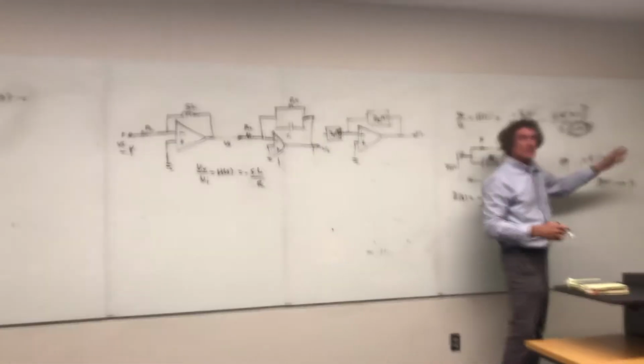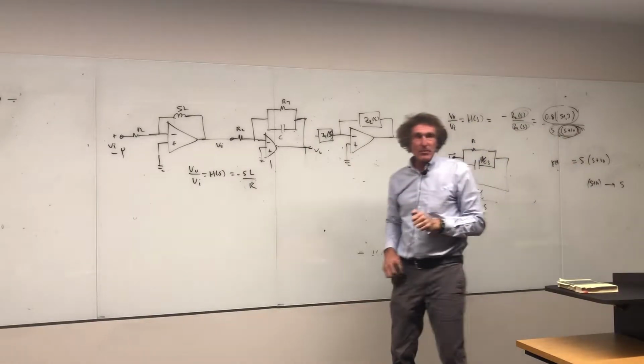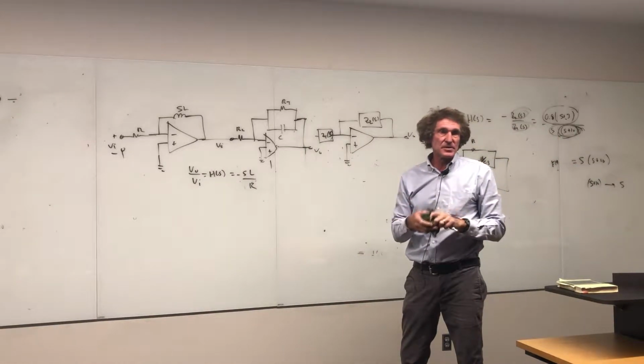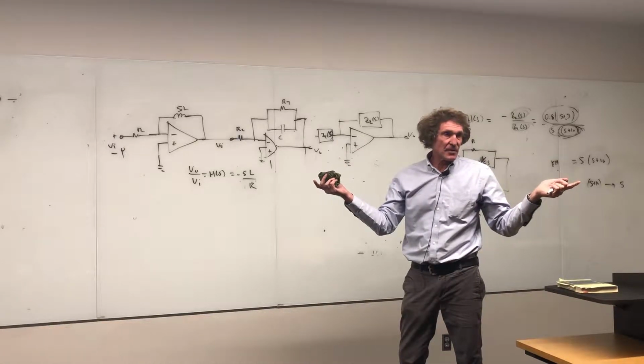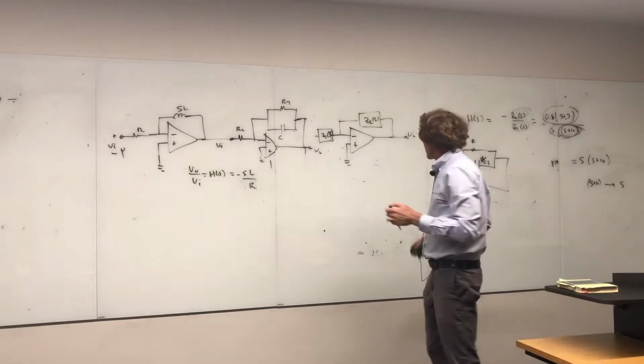I'm going to stop right there. I'm just telling you, think in terms of operational amplifiers with R's and C's to build transfer functions that have multiple poles and stuff like that. It's very easy to do. That's my point about this.